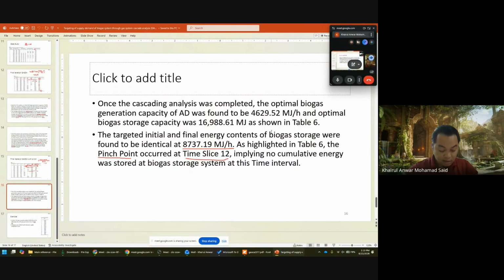So for the initial, it is an infeasible cascading in which Q initial is zero. That one you don't have to calculate the P%. Once we determine the smallest value, which is 508 from the initial iteration, it becomes the Q initial, then it becomes the first iteration for a feasible cascading. That one you need to calculate the P%.